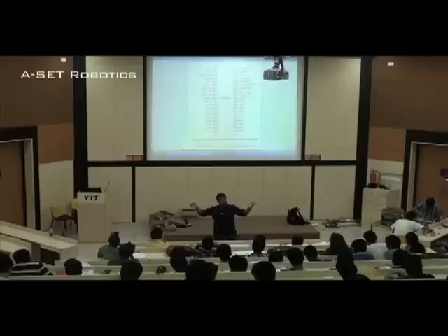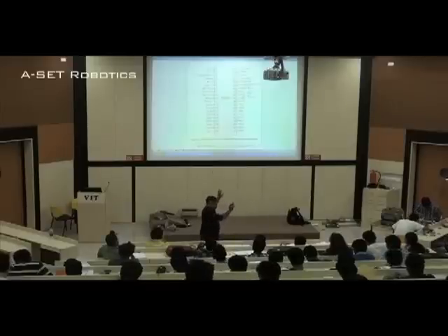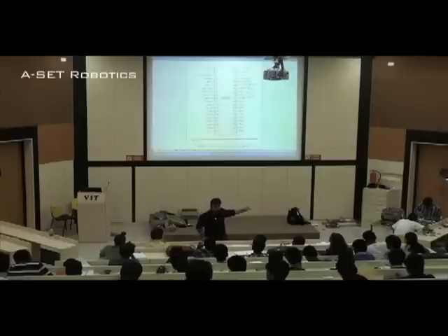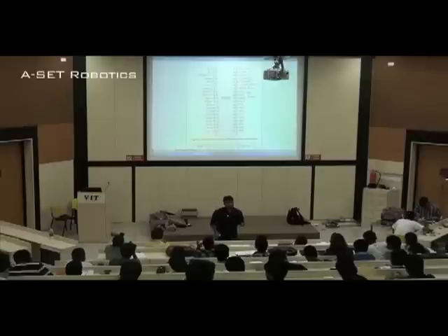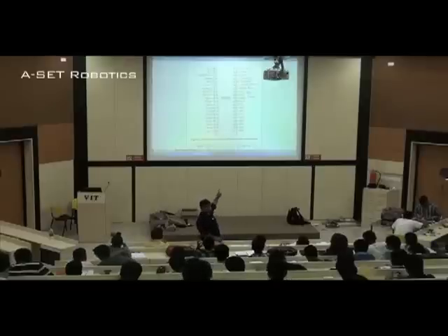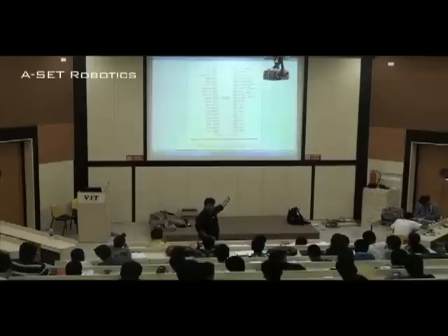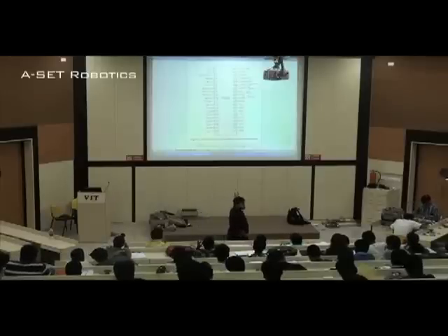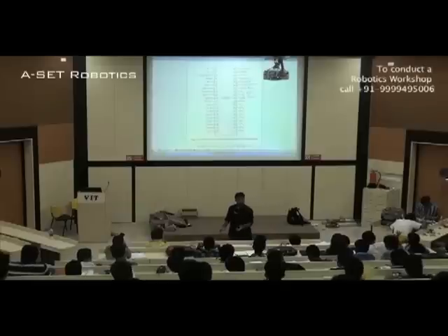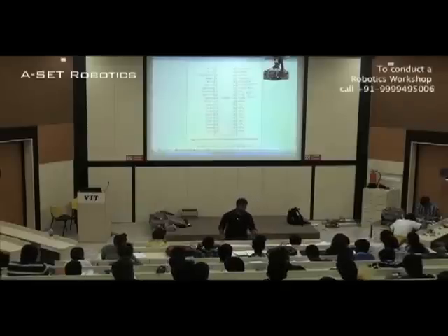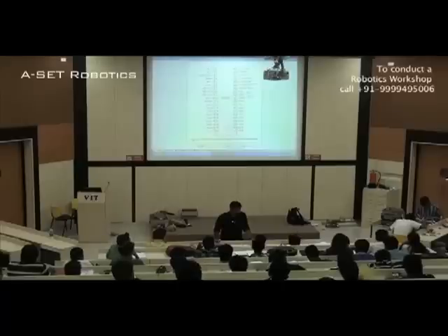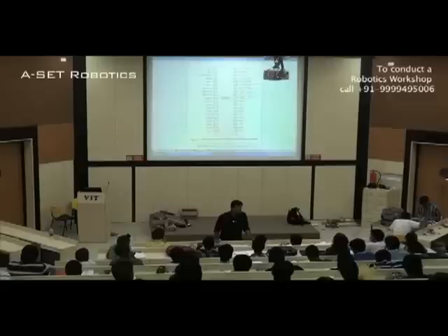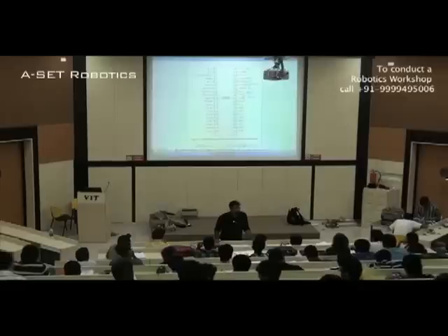And when the memory is not ready, the microprocessor will go into wait state. It will say, okay, I'm waiting, I will wait until you finish. And whenever it is ready, it will give a one signal. It will set this pin high, and the microprocessor can do the further work. Clear? Why only read and write for all of them? It's generally associated with memory. With any other I/O devices, there's an I/O controller, and an interrupt controller that controls it.